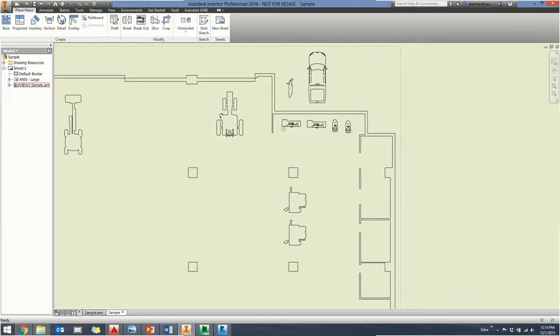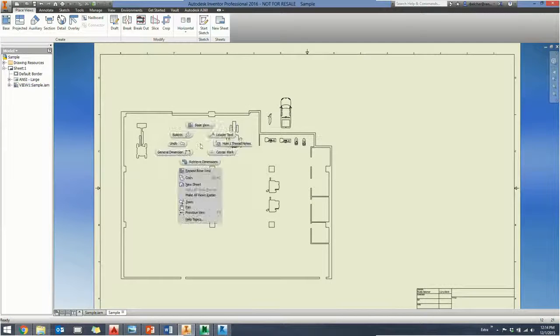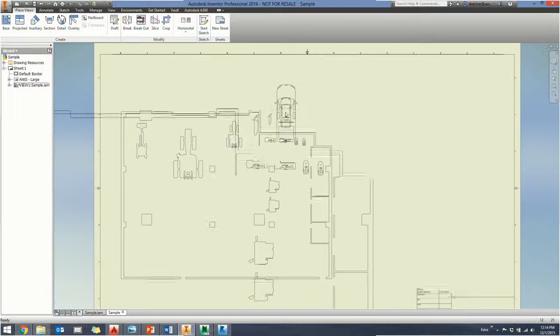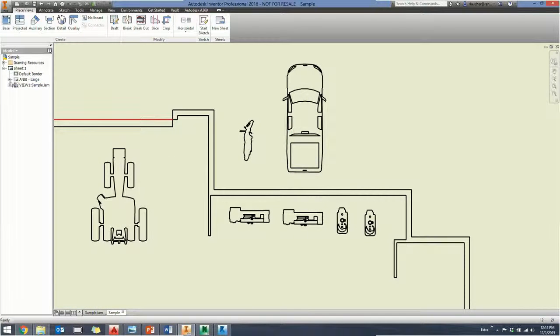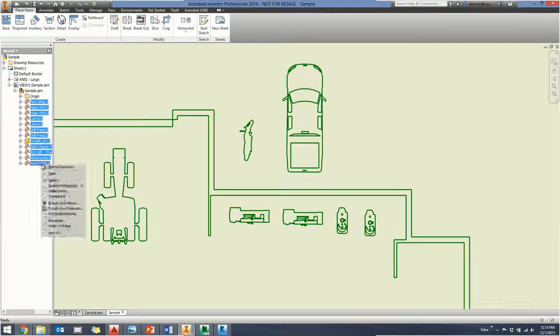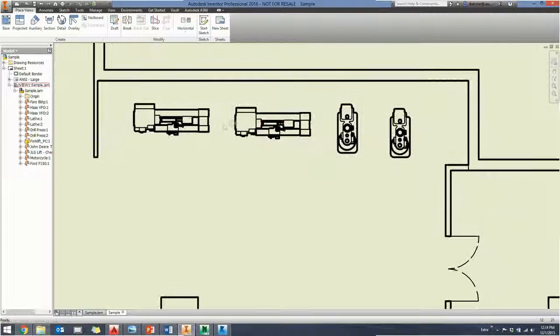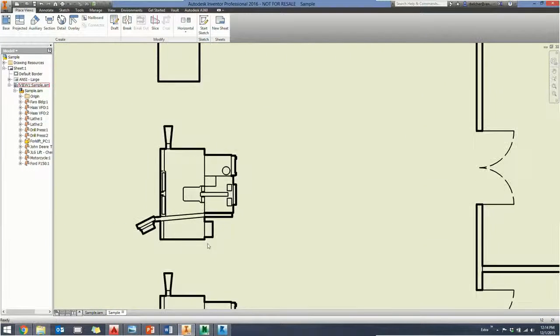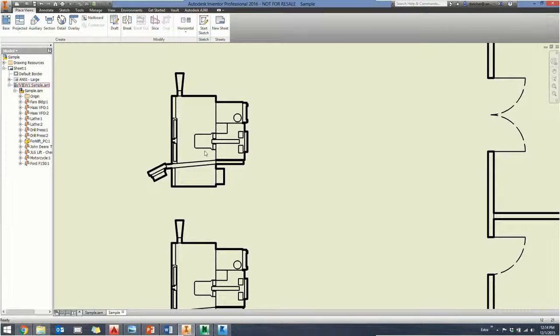And I can generate all of my line work from all of those assets at the same time. So I have the same ability to generate CAD data from my point clouds now. And they can be as detailed as you want. You'll notice that these are fairly simple. If you take the time and draw extra lines on your footprint, you can get that data and bring that in. So if you wanted these to look better or more accurate, you can add your own lines on top of that footprint.